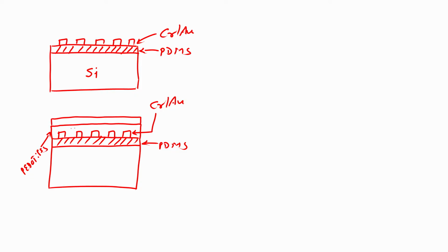So, we have photoresist spin coat, and this photoresist is again a positive photoresist. After spin coating the positive photoresist, the next step is soft bake. Soft bake at 90 degrees for 1 minute on a hot plate, followed by mask. You load the mask and then you form the piezoresistor.